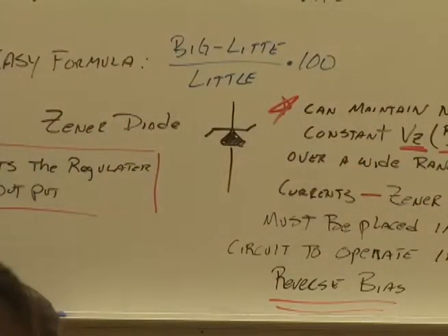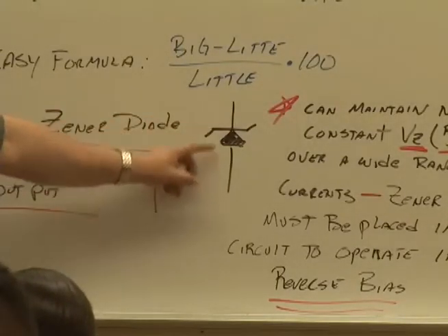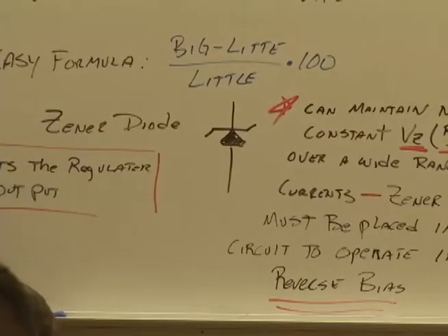It's the same thing. If you remember that DC characteristic chart way back in BEC, everything on the left side was all the reverse stuff. Reverse breakdown voltage, reverse current, all those things. That's where the Zener likes to operate. So if there is a change in the Zener current, its job is still to do what? Keep that switch open. Open switch, max voltage, right? Yeah, that reverse.